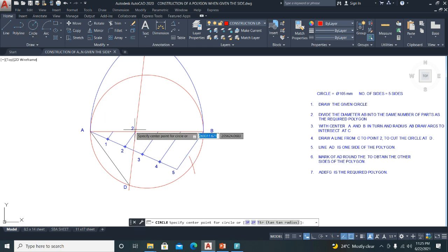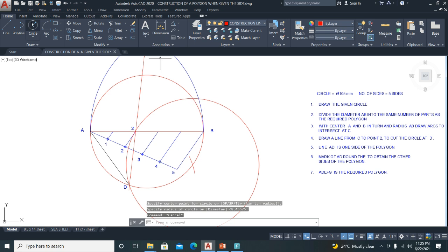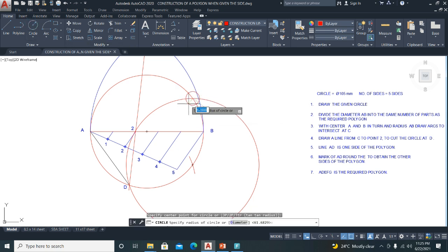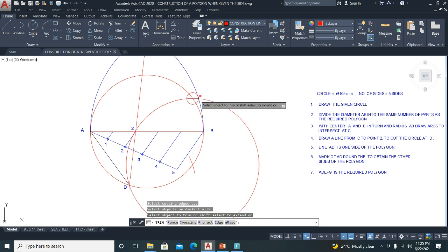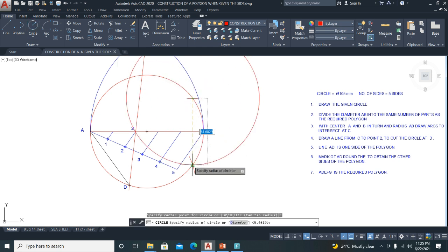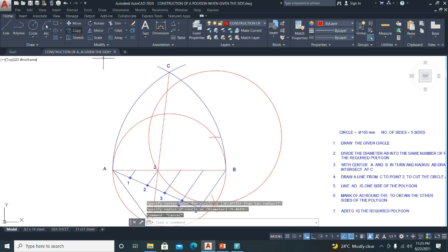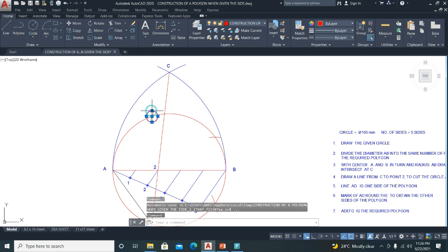And you're repeating that process from here. So you will obtain this spot. And one more time, here, open it to this spot. Drop your circle in. Trim out the little rest of it here. Trim, enter, and here. Select, delete it, and delete it.